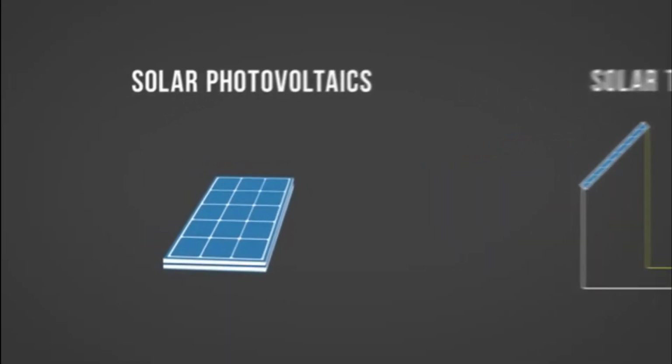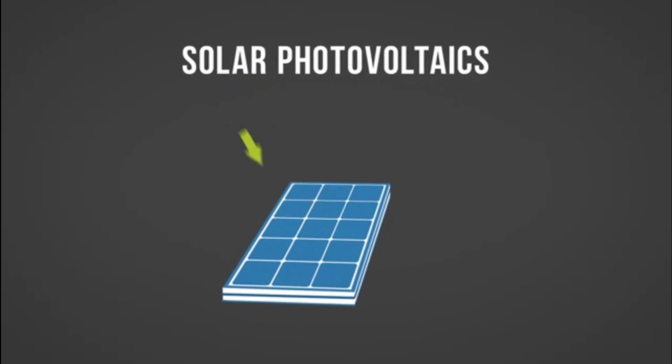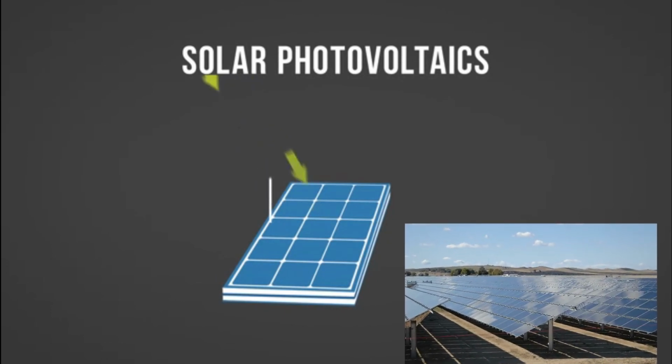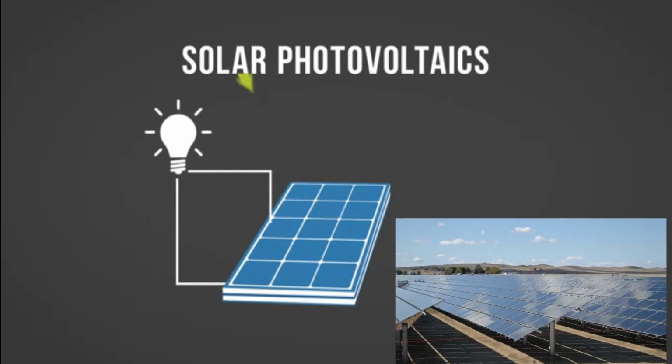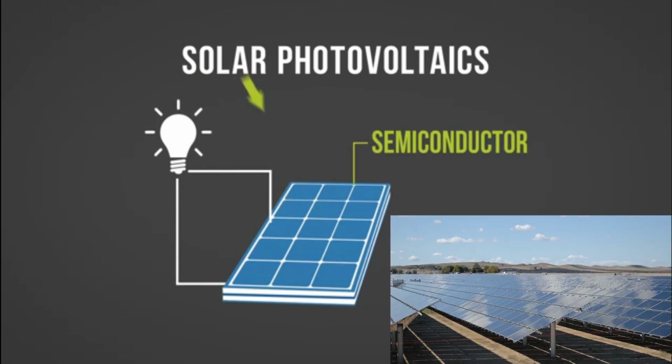Solar photovoltaic, we also call it PV, converts sunlight into electricity. A large number of PV panels are laid out on flat ground and directed toward the sun. The panels generate DC power after absorbing sun rays. Then the DC power is converted into AC power through power inverters.